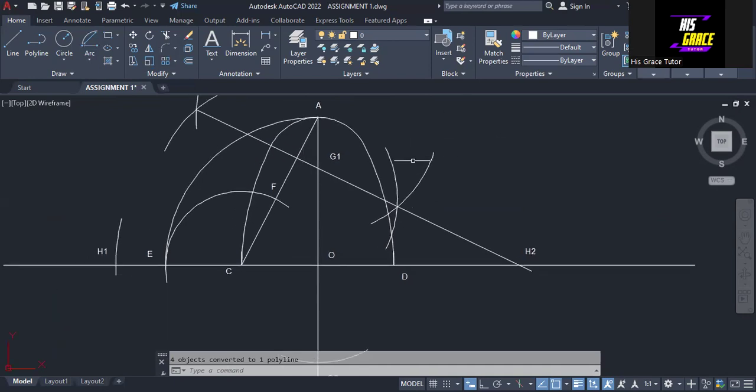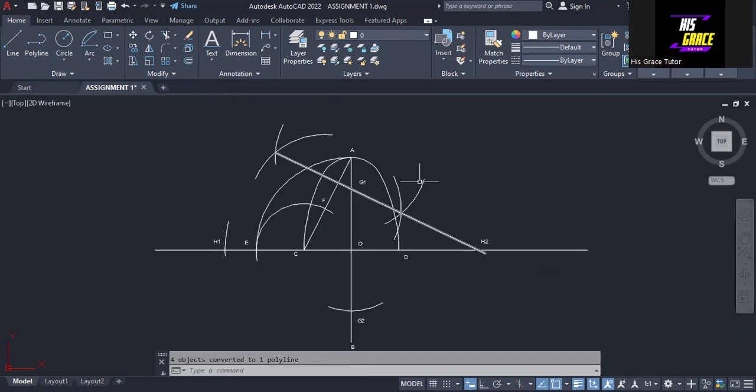All right, so we are now going to mirror the whole of this so that we can have it down here. So how do we do that? I will click on mirror. Select the object to mirror. Then I will right click. Then I will click on this horizontal line. So it comes like this. Take it easy to this point. Okay, so we have it like this. So click on select no. All right, so we have it like this now.